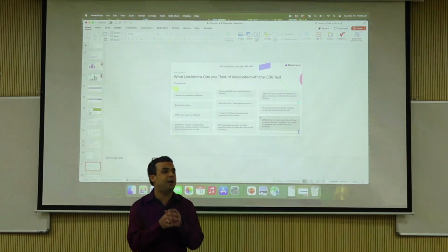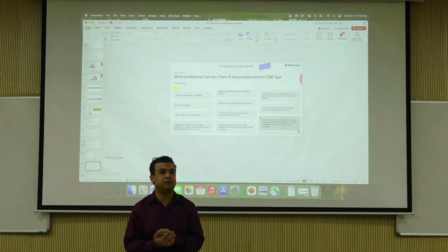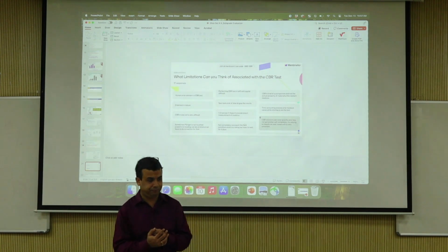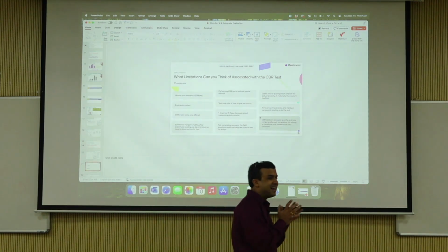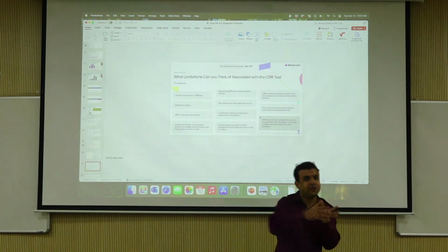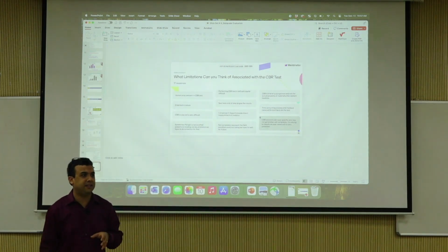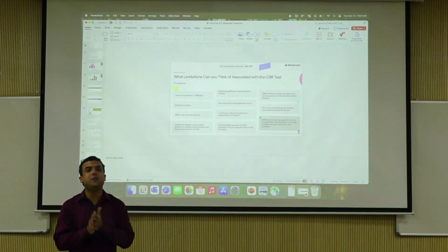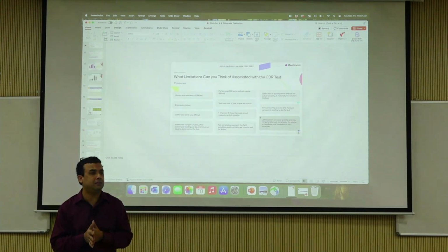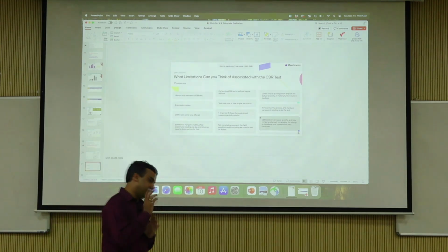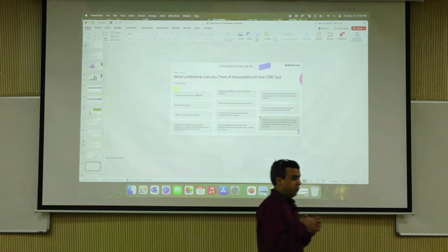So you have a steel plunger that is going into the soil, right? When was the last time you saw a steel plunger going into an actual pavement? No. It's a bearing capacity kind of a test. It's California bearing ratio. Everybody has taken geotech classes, I'm assuming foundation classes and stuff like that. So capacity is stuff like that. Do we design pavements for bearing capacity failure? No, we don't, right?